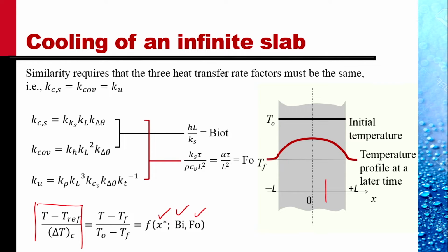it has been solved by writing this non-dimensional temperature difference dependent variable as a product of two factors. One, a factor where we determine this function at x star equal to 0, and we multiply this by a correction factor which depends upon x star and Biot number, hopefully.